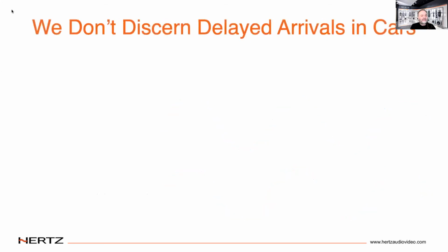This was something I didn't understand for a long time. The farthest speaker away that you can put in a car is still not far enough for us to notice that it's farther away. The two sounds will combine at our ears and sound like a single sound. It'll just have that ragged response we showed you earlier. There won't be any echoes or anything like that. So you need processing to handle that sort of delay. The distance from the speaker is not going to make it sound like two arrivals.